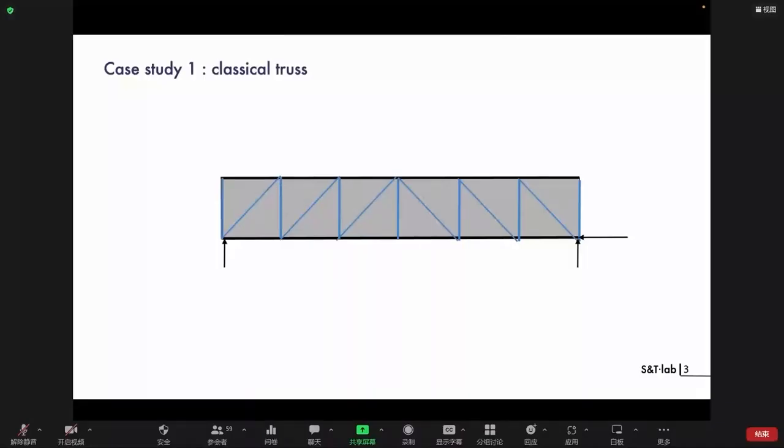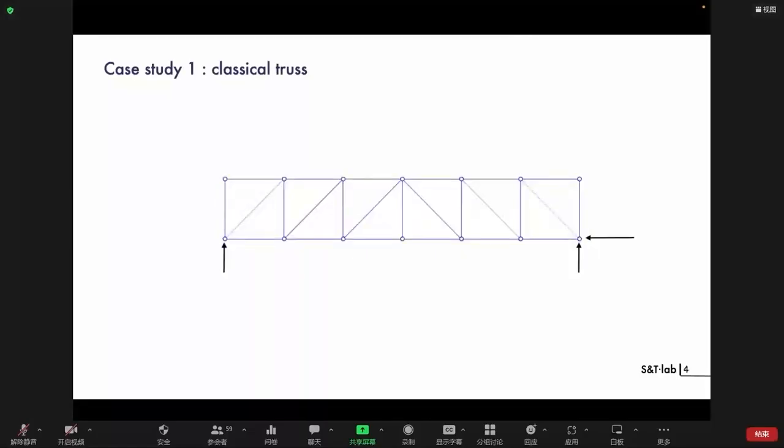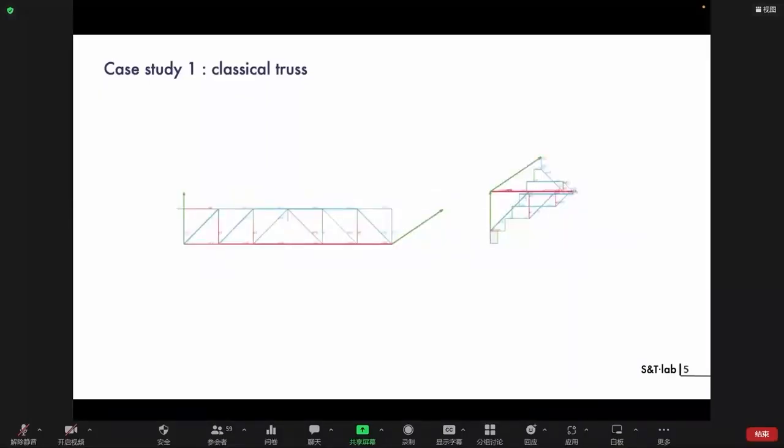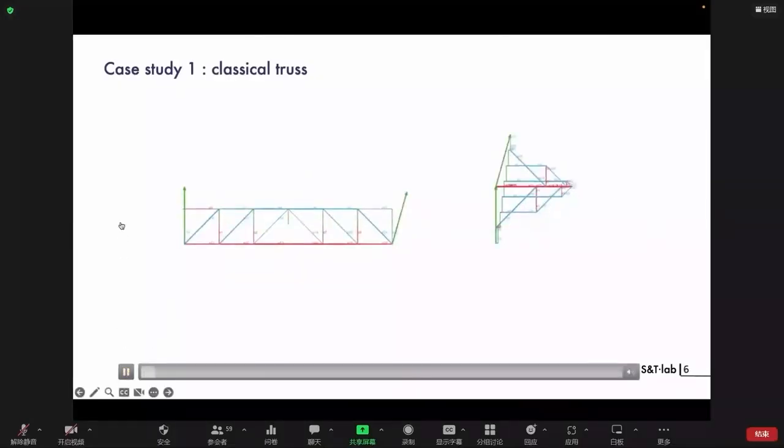It could be, for example, a beam in CLT. Because of the anisotropy of wood, it's quite interesting to use CLT. And if we compute it with Rhino, and we feed the data in the Grasshopper plugin, VGS, we find a form diagram and a force diagram on which we can make some manipulations, and I will show you in the video.